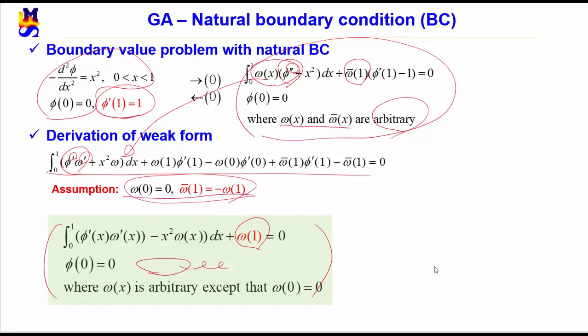What we have to consider is only the essential boundary conditions, that can be easily accomplished by FE approximation, that is, interpolation function, which will be studied soon. Of course, finding the trial function which meets only the essential boundary conditions of actual engineering problems on a 2D plane and in 3D space is almost impossible without any technique like FE approximation. It had been the problem of conventional theoretical approximation methods of boundary value problems for the sake of engineering application.